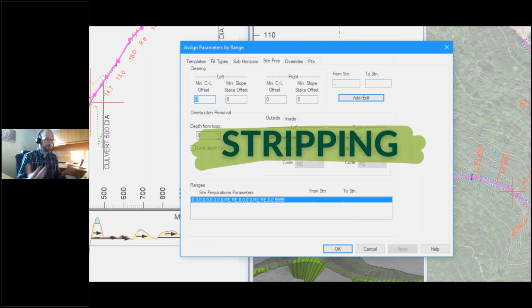So if we clear that out, we're going to give area to add storage for snow removal. So we can wing back our snow banks in the winter, which reduces barriers for wildlife. And then it also increases sunlight on your road, which can be beneficial to dry things out quicker. So you reduce the risk of things like rutting. And even if you're not rutting, there's just less water on the road getting mucked up by tires and producing sediment and being transported to places where we don't like.